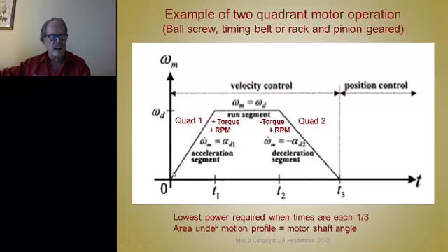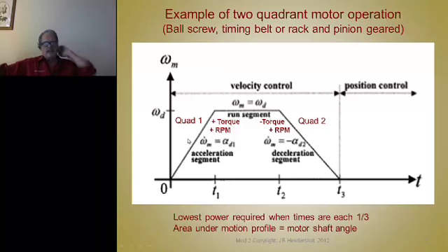And by the way, this sort of a trapezoid is a very close approximation to the shape of a parabola. I guess I should have drawn one on top of here. But for an angular positional move, a parabolic move is the best, but a trapezoid makes it easy to control. So a third of the time, to make the trapezoid approximately the same shape, we could accelerate slower.